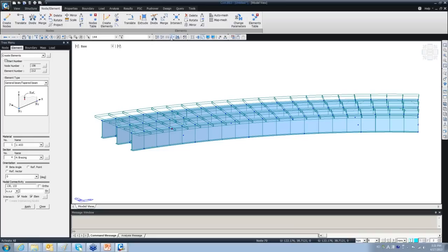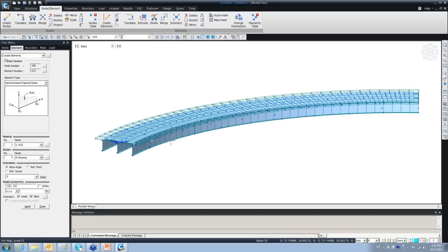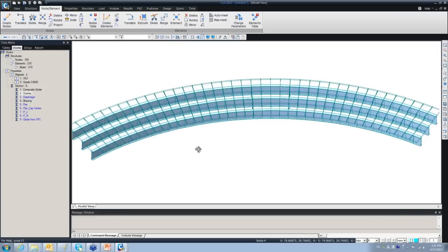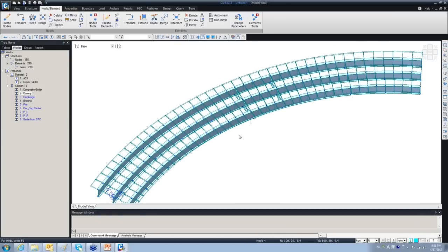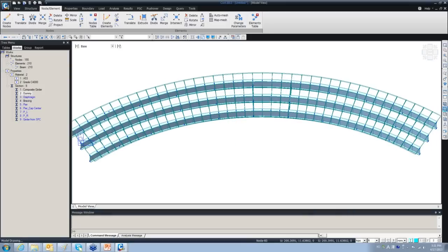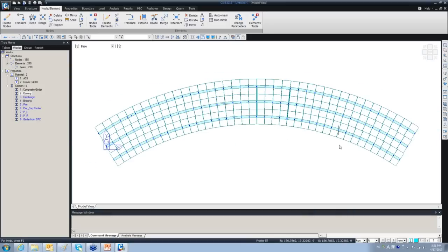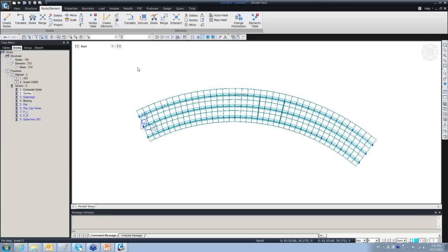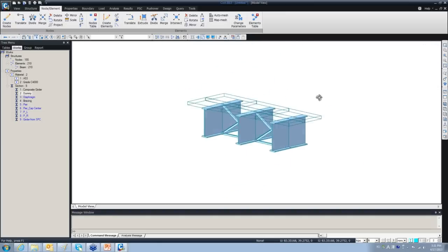All right, so let me activate the entire structure and turn off these dummy beams. So let's see, imagine that we got all of these. Now what I'm trying to do, I want to define these pier cap and then the pier for you. Okay, so I want to place the pier cap underneath these guys. So I just activate this part of the structure and say activate.